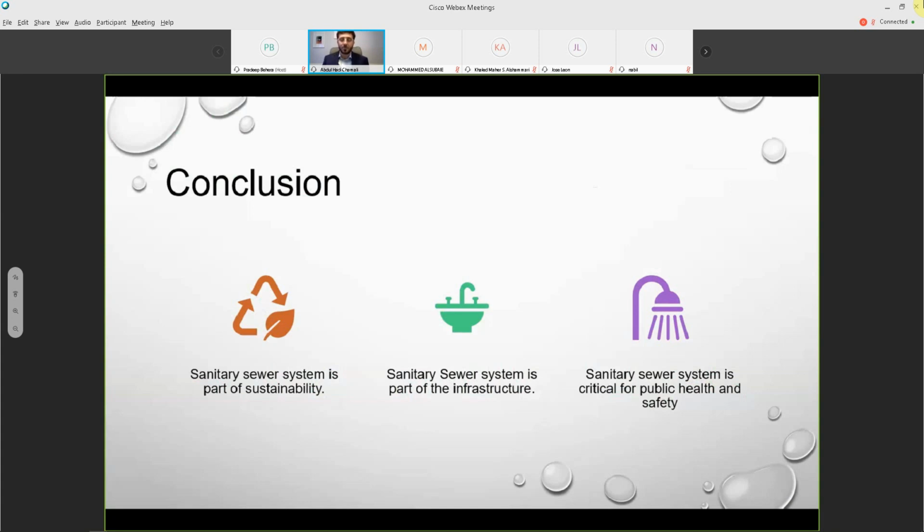you don't have a good system. You don't have a big enough pipe to take your discharge. What's going to happen when you use your shower? That water is going to come up in your bathroom. That water is going to come up in your kitchen, and that is very important because if the public complains, that's going to be a really big problem for us. So that was for the sanitary system design.